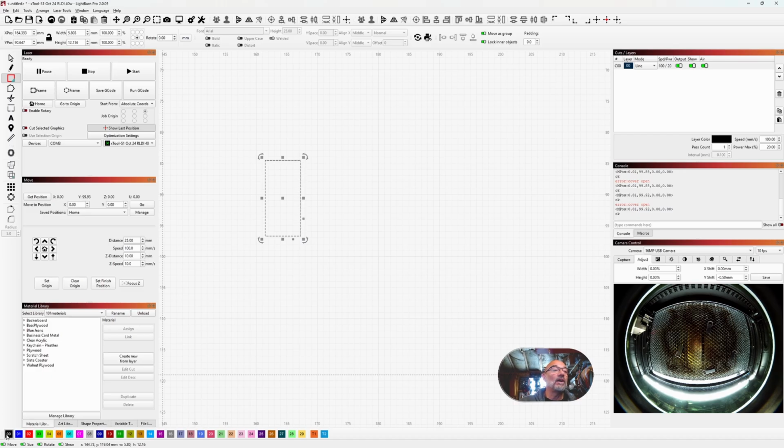We are, if you notice, on this black layer, right? Now say I'm gonna do another one. I'm gonna go over here. I did that, it's still black layer. If you notice black, but if I click red, just so it comes out, you see red? There's two layers here and automatically LightBurn creates two layers. Why is that important? Layers give you the control of your laser.